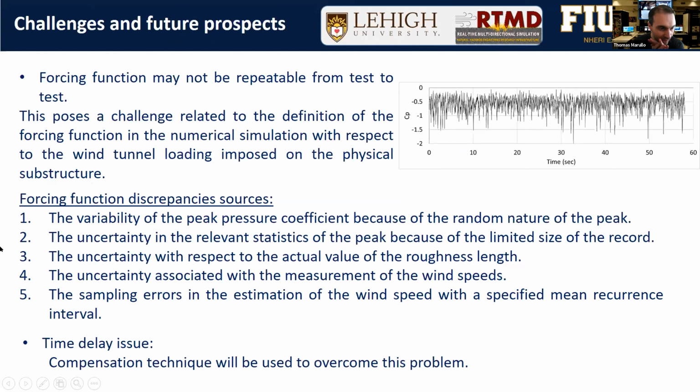Okay. Yeah. So that was sort of what I mentioned with the electric actuators, is that if we're finding that the response over time is not good, we can implement these actuator compensation techniques to electric actuators as well, because we have that built-in feedback transducer. I'm going to be doing some benchmark testing. These are actually in my facility right now. I'm going to do some tabletop tests to see what our time delay is, and we'll see. Then we'll know how to tune the compensator to make it work with our hybrid simulation.